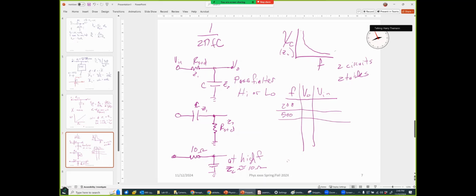And that would mean that the input Z, we've talked about input impedance. Remember, the analog voltmeter has an input impedance of 10K. The digital voltmeter has an input impedance of 10 meg. And the reason is that when we take a voltage measurement, one will have less effect. Now, if I have an input Z of only 20 ohms, V in is going to sag because, remember,